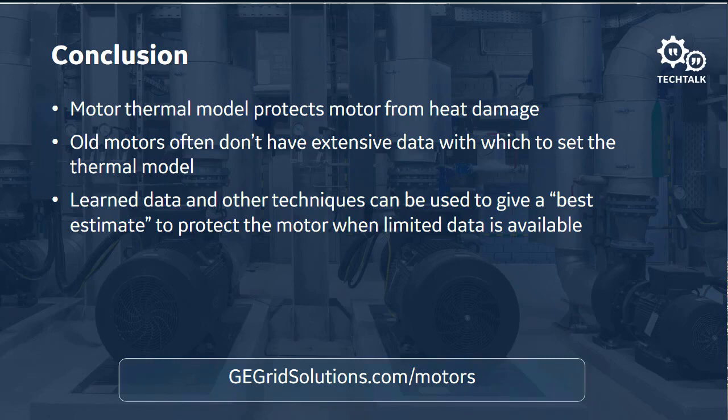It's merely because in the scenario we discussed today, I don't know how conservative or liberal I am in my settings because I've made so many assumptions. So I would tend to err on the side of conservatism in this particular case and not go to the whole 125% that I could go if my service factor was 1.15.